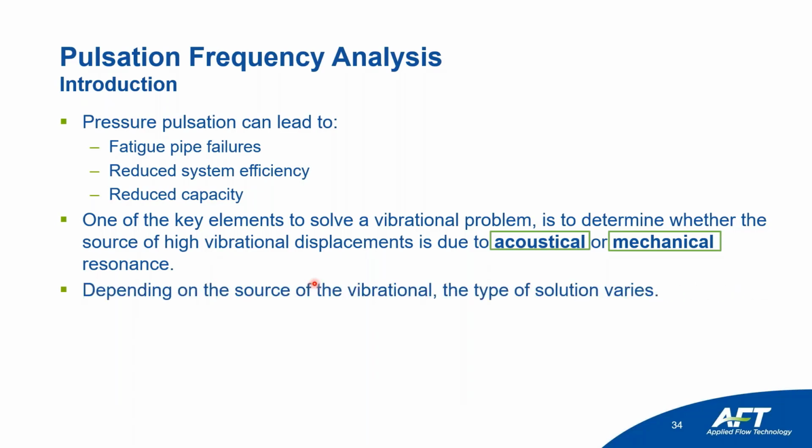Why? Because depending on the source of vibration, the type of solution varies. There are acoustical solutions and mechanical solutions. An acoustical solution could be, for example, using an orifice or using a gas tank. Mechanical solutions are more about improving the quality of your supports.